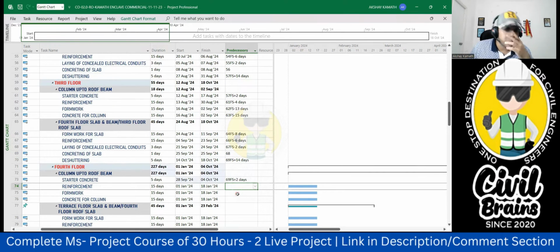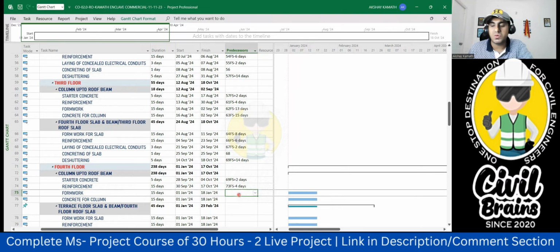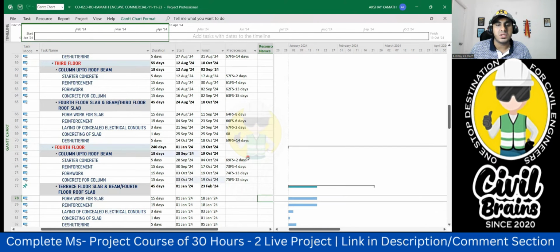And after that, what is that? Reinforcement. Reinforcement is 73 FS minus 4 you will give. So 30 September. So 29 is a holiday, no? Yeah, 29 is Sunday. Good. After that, formwork. Formwork is 74 FS minus how many days? 13 days lead it is. Okay, 3rd October. Concreting is after the formwork. So it is 75 FS minus 15. Okay, good. So both of them will finish together.